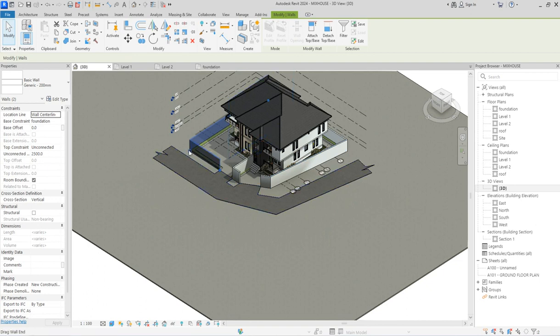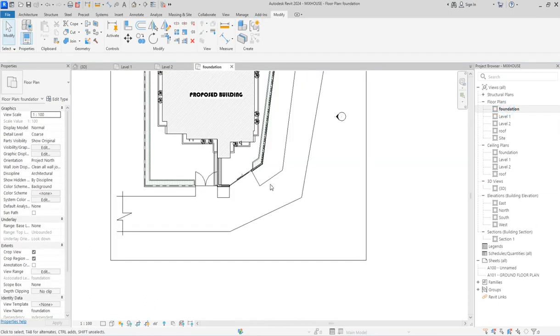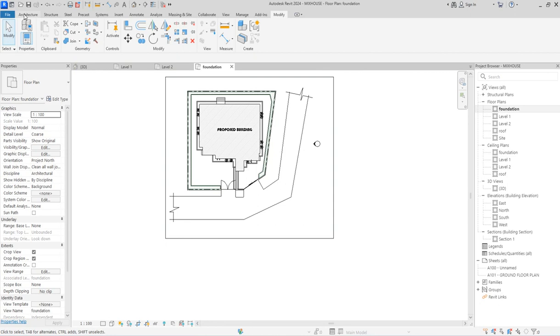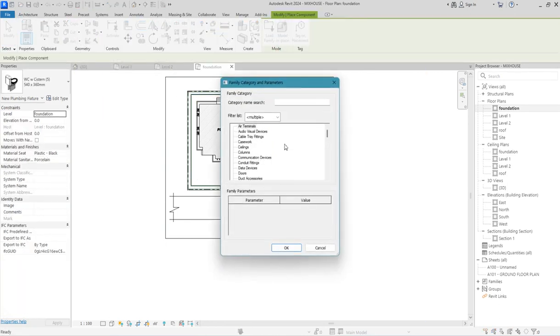So you reduce the size. I want to focus on one side before I move to the next side. So click here and say reduce the size to 1800. Good. So let it go down. Now you go to this place, then you come on and say click and model in place component, model in place.